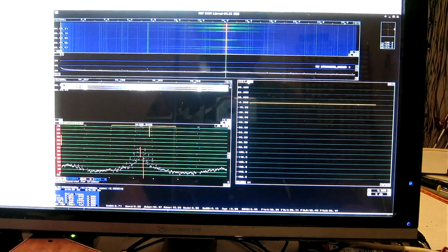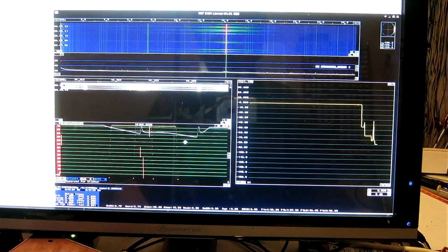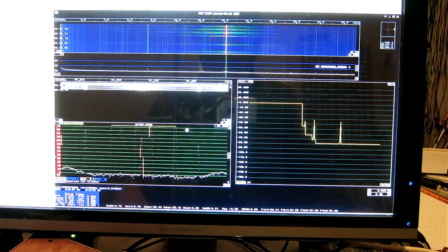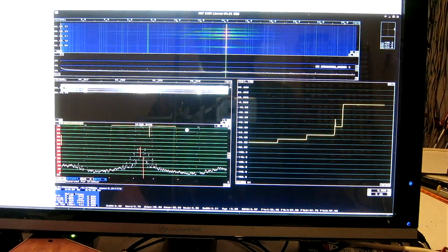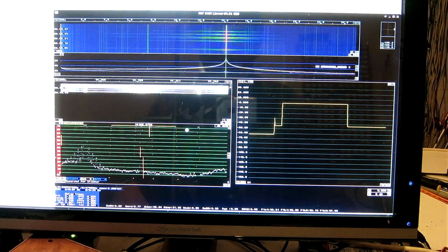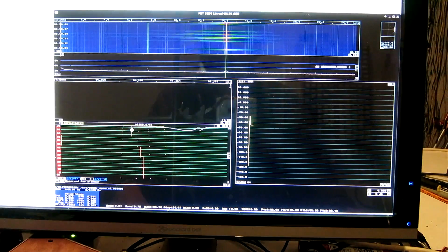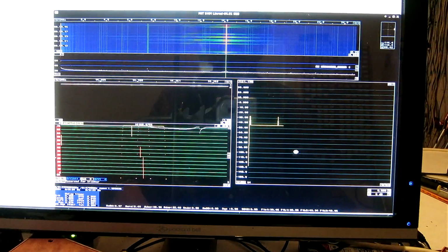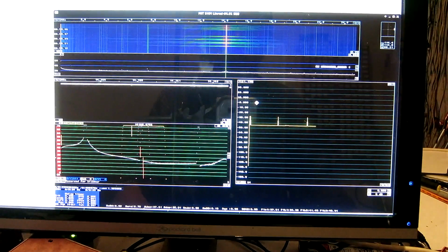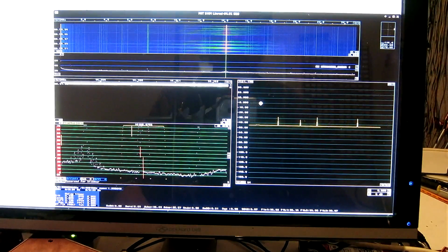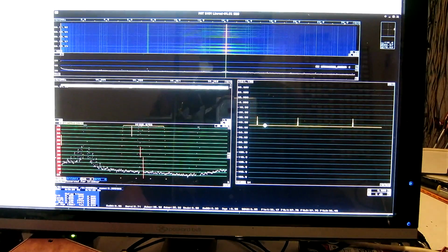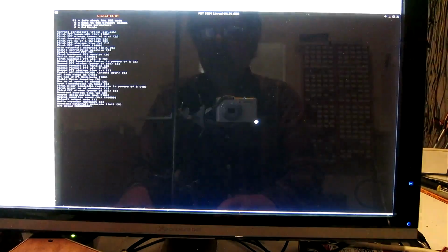21.19, and then look at the spur, the resampling spur. Was going too fast. That's the signal, and here is the spur. I make the bandwidth a little bit narrower to be sure I don't get anything else. And now you can see that even though the resampling is 12, meaning 2 to the power 12, the suppression of the resampling spur is no longer 3 dB, it's 43 dB.